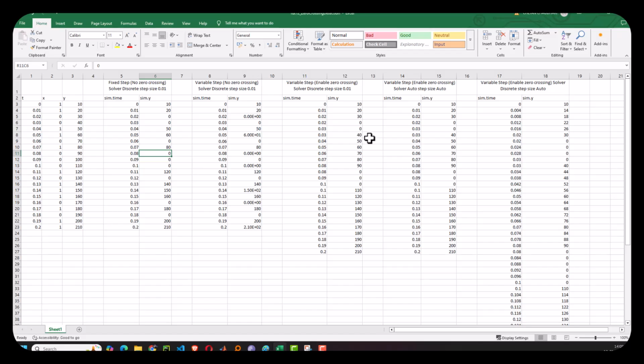Now in the third simulation, I selected my solver as variable step and enabled zero crossing detection in the switch block. The rest of the properties I kept as they were. But here, in simulation three, if we see, the steps are more, right? Why did this happen? Because when it was 1 there was a good solution, no extra processing. But when this 1 changed to 0, for the first step it was 1, for the next step it was 0. This is called my zero crossing detection.